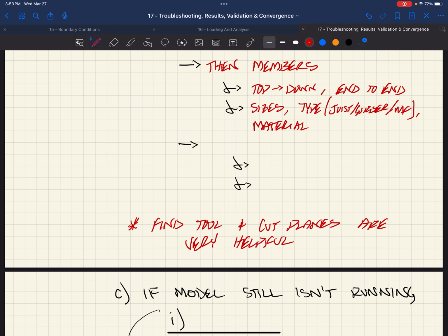One thing I would say is that, that yield stress, material stress warning can play a role in the structure if we're thinking about stiffnesses, right? So if you decided that you modeled a 4-span continuous beam with a 2x4, it's going to say, hey, you've exceeded the stress of a Doug fir, and then you say, well, I'm going to model it as steel, right? You're going to get the same results there because the stiffness is consistent throughout the continuous beam.